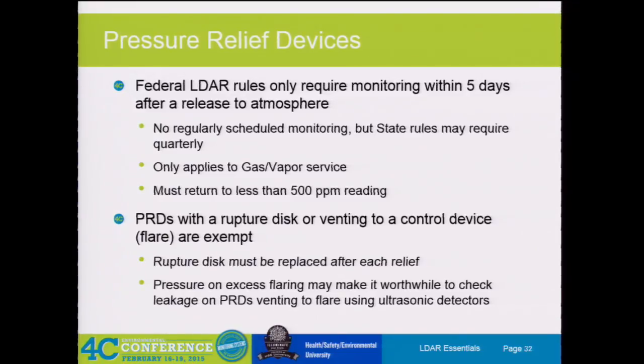And usually they'll come back and say, oh yeah, this one goes off all the time, and this one popped over here. Then you go back to the LDAR trailer, because you go up there, you look at the PRV, it's identified, tag number 7. Hey, can you pull me tag number 7 in your crude unit or wherever it might be? When was the last time you guys monitored? Oh, well, we haven't done this for this long. Well, the guy said that this popped just 3 days ago. And then he said it popped 2 weeks before that. He has documentation that shows it popped because he had to go back up there and set it.